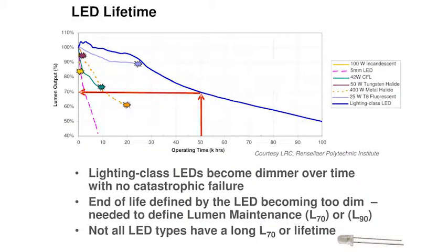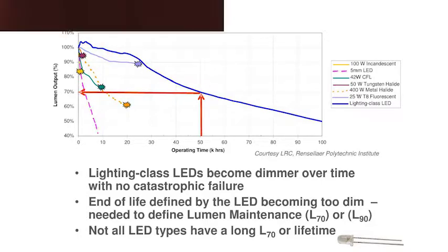Most people don't know that an LED light actually increases in lumen output for about the first 1,000 hours. So it goes up and then it starts to gradually go down over a period of time. In this case, that one was showing a 50,000 hour life cycle of an L70 for an LED light. We deal in terms now of L90s. Most of the time, depending on the temperature that we're operating an LED in, I'm going to tell people that 10% of its lumens are going to be gone at this period of time.